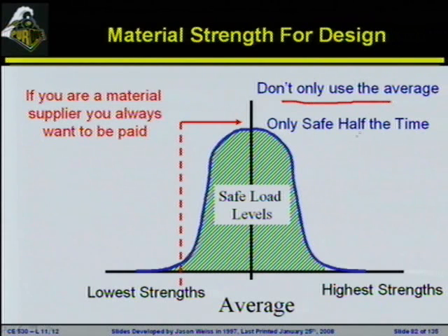What we're going to do is we're going to design based on some sort of a lower limit type of analysis. Now, we're not going to ensure that 100% of what's made is above this average, because statistically that doesn't make a whole lot of sense. But what we want to do is we want to actually start to try to design our materials, or we want a different target strength than the required strength that we would have in our particular structure.